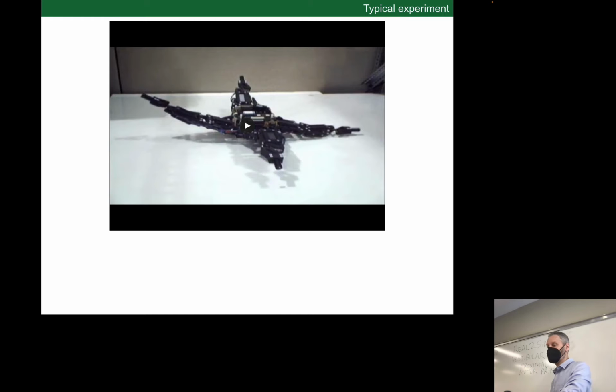How is that final evolved model housed in the robot? What do you mean by housed in the robot? Like, how is that stored in memory to the point where it's useful down the road? Good question. So in 2006, we could not run this on board the robot. So we were just communicating to an off-board device. Once it has an accurate simulator, we're going to do what we normally do in evolutionary robotics. We're going to use that evolved simulator to evolve neural controllers off-board, not on the physical robot, and then send the best evolved neural controller to the physical robot.